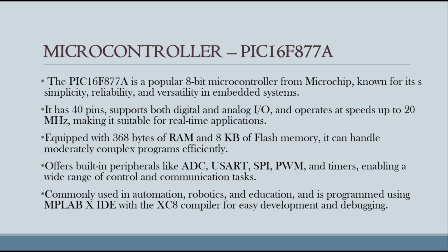It offers built-in peripherals like ADC, which stands for analog-to-digital conversion, UART, the universal asynchronous receiver-transmitter, pulse width modulation, SPI, and timers, enabling a wide range of control and communication tasks. An example of the timers is the watchdog timer. It is commonly used in automation, robotics, and education, and is programmed using MPLAB X IDE with the XC8 compiler for easy development and debugging, as we have discussed in the previous slides.